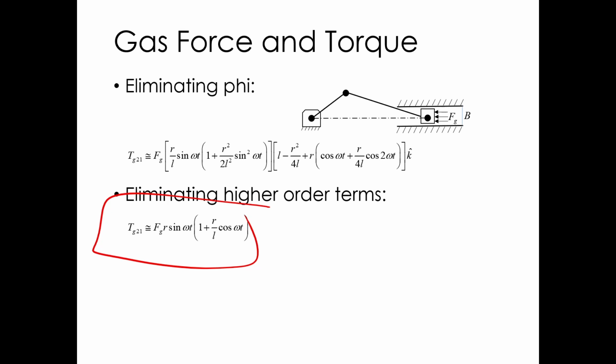I went through that pretty quick and not in a lot of detail. So here are the limitations of what we've done here. We've come up with some approximations, right? We've used a few approximations, including the 2 force member assumption. We're not really considering the mass of the connecting rod, or don't really have any ability to do anything with offset eccentric weights on the crank. So we get some understanding of why R over L should be what it is, and why we only have to worry about, in general, primary and secondary vibrations, but we're losing some information here with these assumptions.